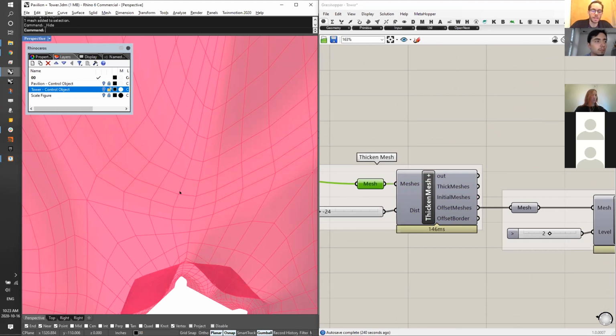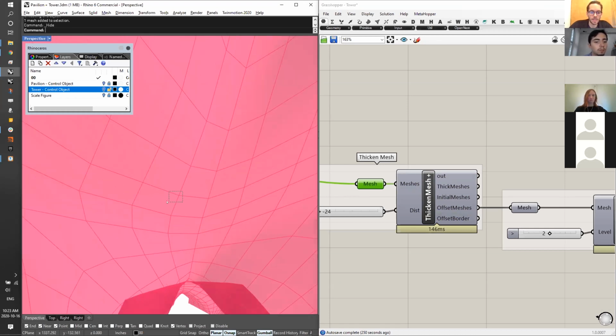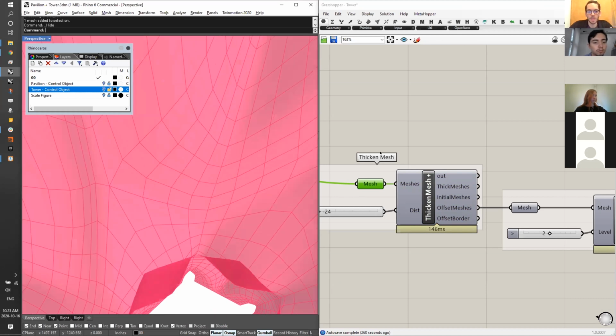You can get mathematically accurate with it by calculating the normal in relationship to its angle to its connecting neighbors. Basically, I take this point and check that point, that point, that point, and I check those normals and see the angles, and that can inform me. It's a little bit of a trick, and that can inform me of a more accurate offset. Alternatively, offsetting surfaces or meshes or B-reps, which I'm sure everyone has tried, can get really messy really quickly because that's again a much more complicated mathematical equation.